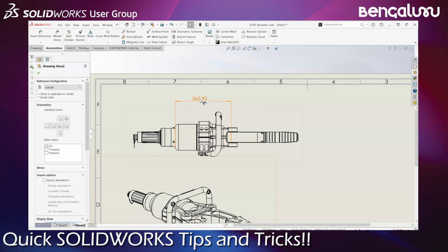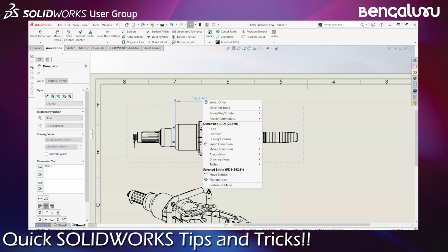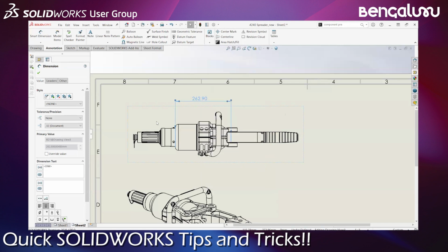And the next thing is, if you want to reattach this dimension to a different edge and not this one. Initially the process was you select the dimension, then you get this blob, and you have to Control-drag it to a different edge. But the problem with that method was it was hit and miss. Sometimes it snapped, but most of the time it didn't. So what we have done is, once you right click, you should see this new option called Reattach. Once you hit Reattach, we are going to highlight